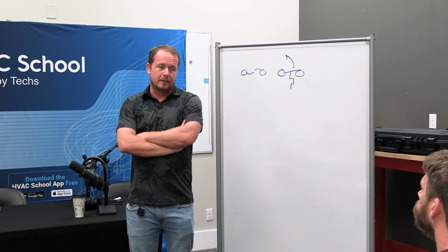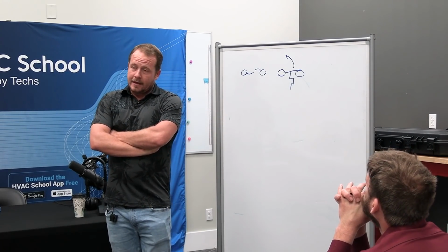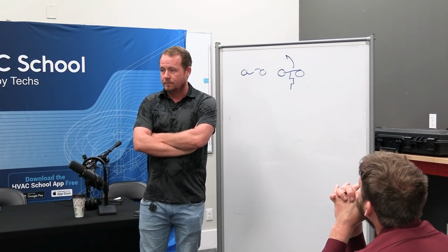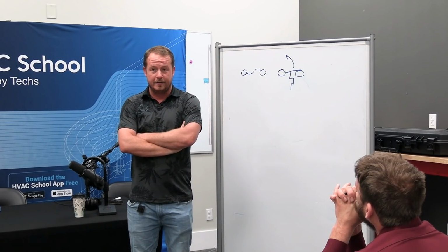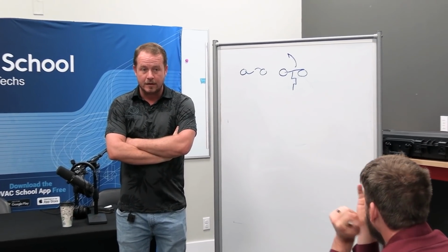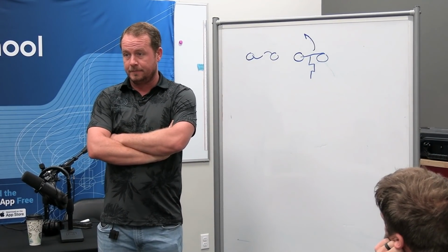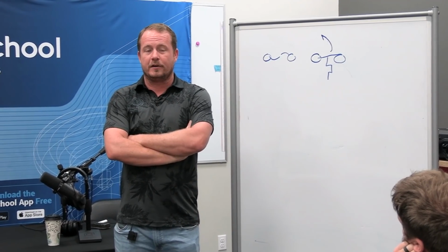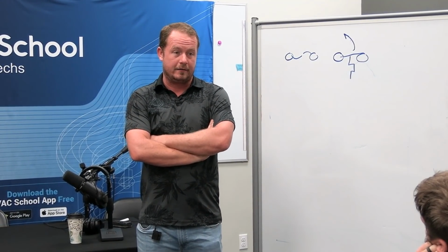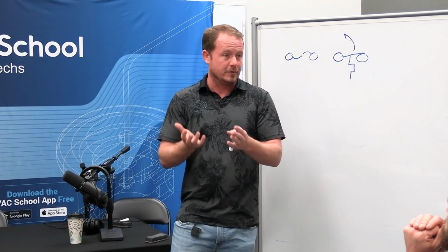What are some reasons why a compressor could be out on thermal limit? Dirty power can be. Failed fan motor. Failed fan motor would be a big one. So if you walk up and you don't hear anything, you could have them both off because of a failed fan motor. So you walk up, fan motor's off, and then every so often you hear the compressor start running, and then it shuts off again, because it overheats since it doesn't have the fan motor to reject the heat.